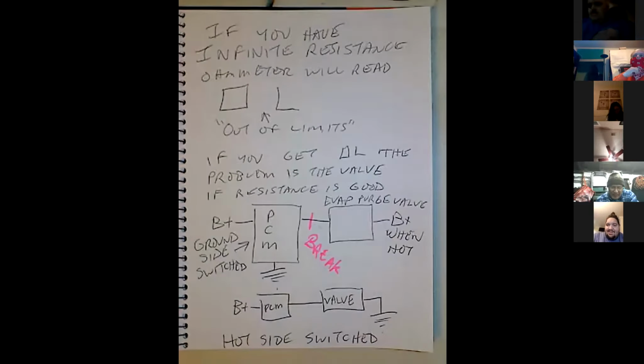What's kind of getting me is that the code said that the possible fuel gas cap is not working. So that kind of really points you towards there's a leak somewhere. Well, yeah, but when you have a gas cap problem, usually it's EVAP system large leak or EVAP system small leak.